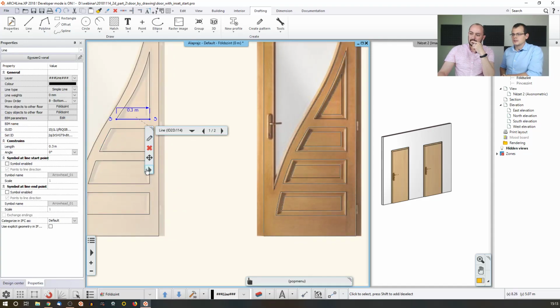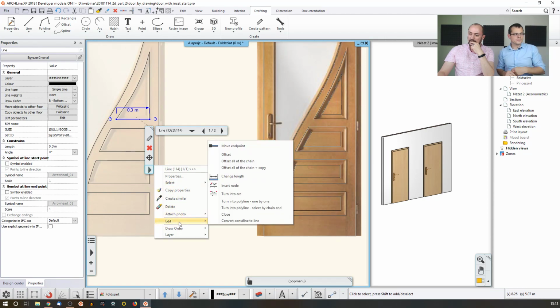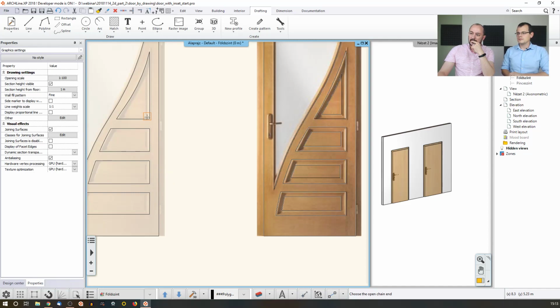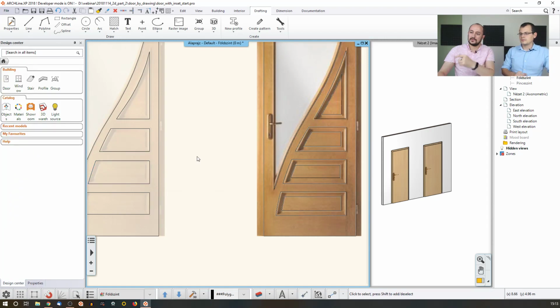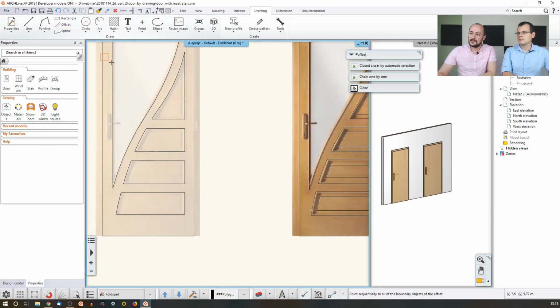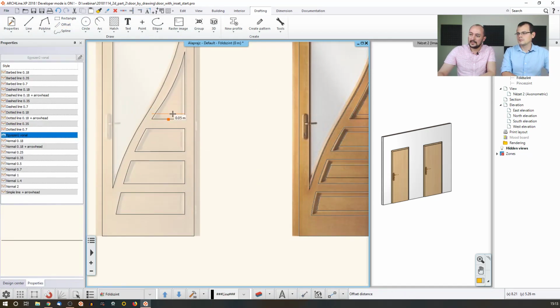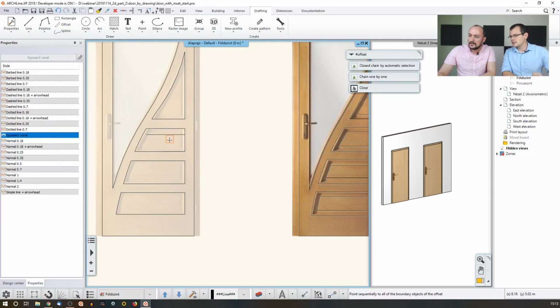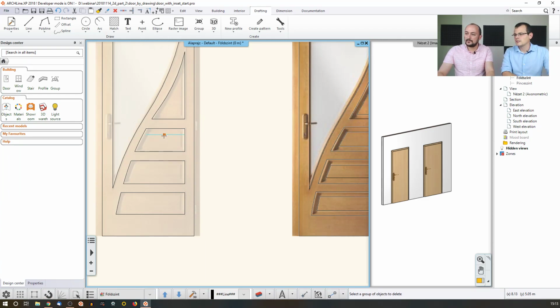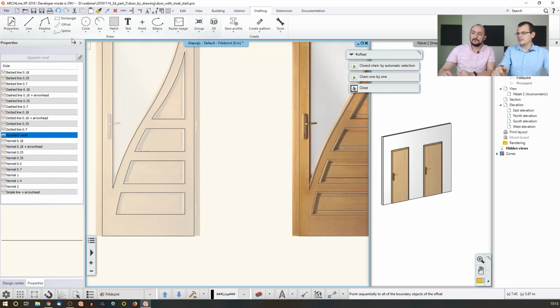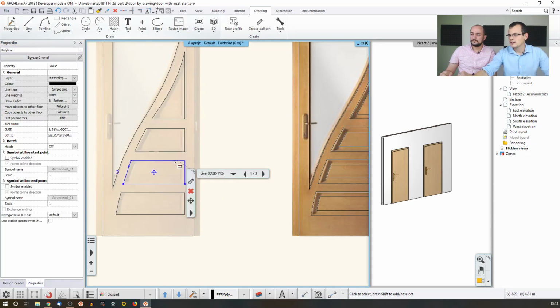Yeah. So again, let's just do that again around, because I would like to speed up my work and turn this into a polyline by just simply recognizing this and this and this and this, and now I have closed loops, and I can go and use the offset tool, and here I can, well, this is. You have to go with offset tool. Yeah, sorry. If you click on this, you should have an offset tool. Yeah, that's here, right, we go.